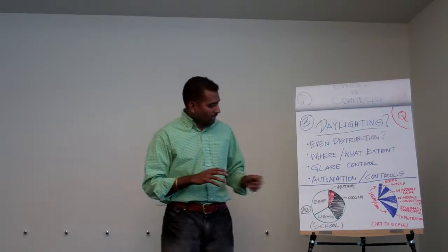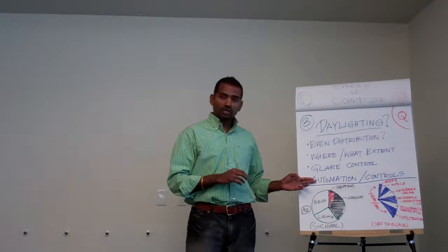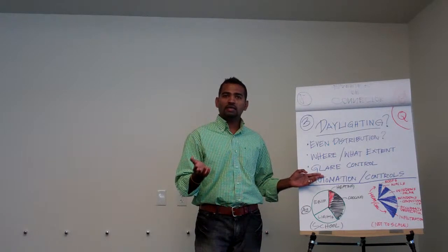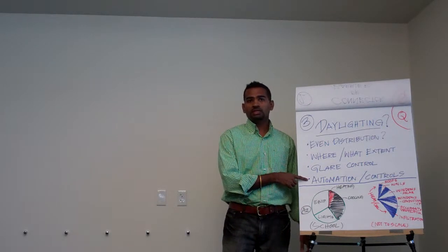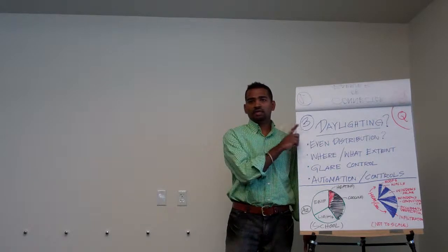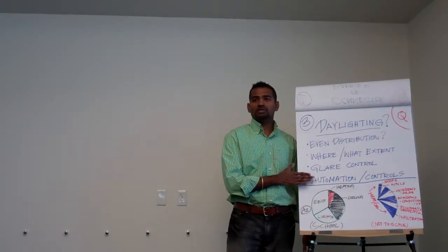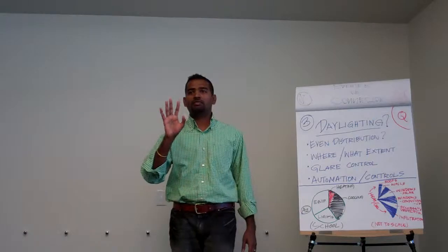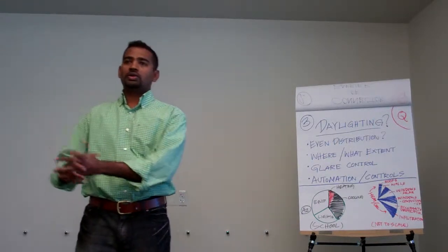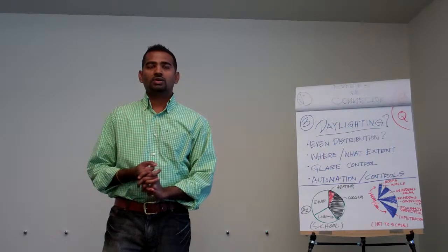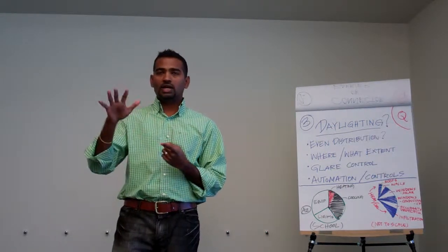Right. And then the last one, if they're really interested in EUI, energy savings through daylighting, if you don't do this piece, there is no use in using daylighting. No use in doing any kind of daylighting strategies if there are no automations or controls to stop your light from turning on, because then you are relying completely on your users to do that. So again, that's a switch on the lighting side.